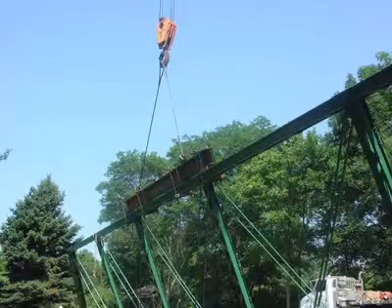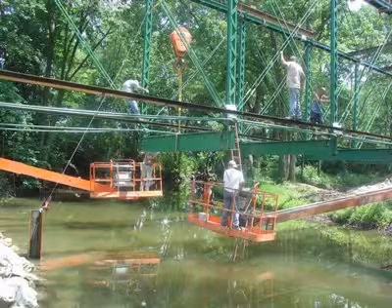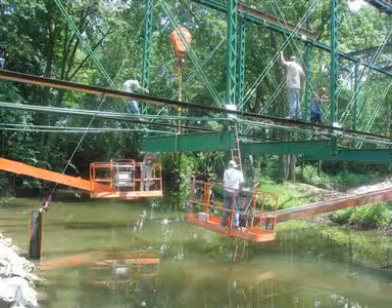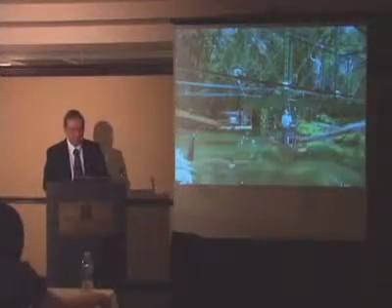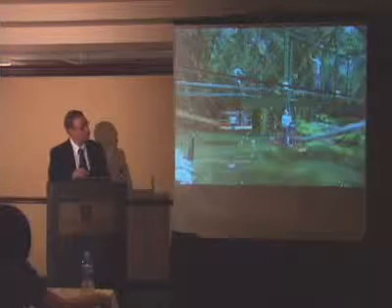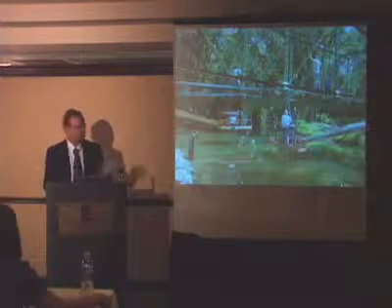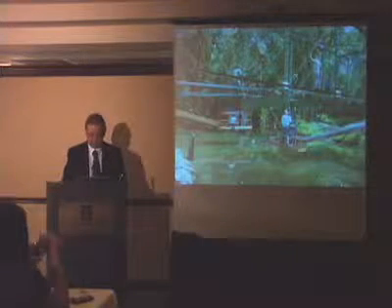And again, the lifting beams were the same as when we took it down. And the floor beams were stiffened by adding bolt-on plates, top and bottom flange, and new U-bolt hangers. There were 4 vertical bars for the floor beam hangers on each end.